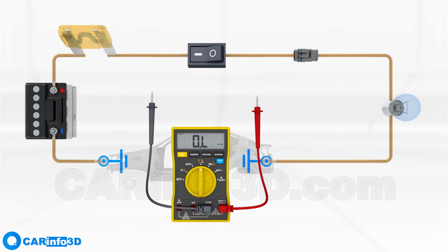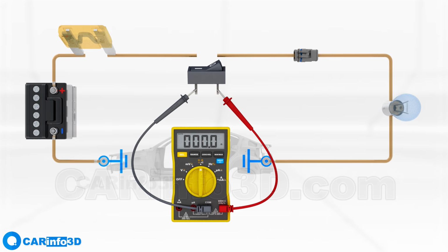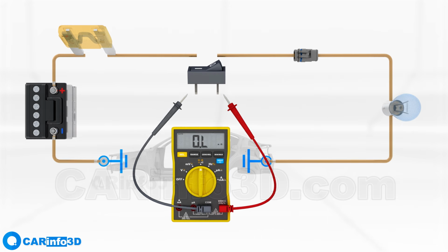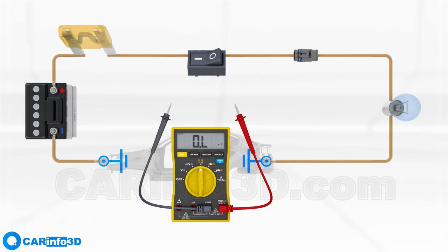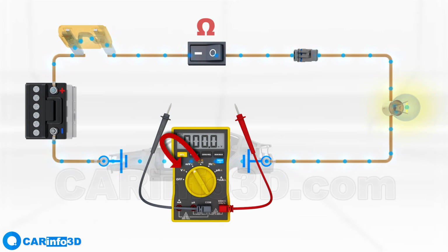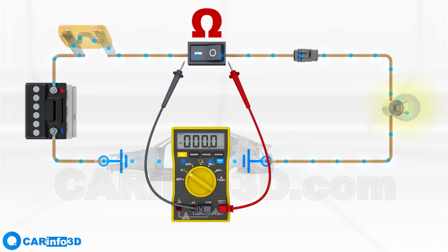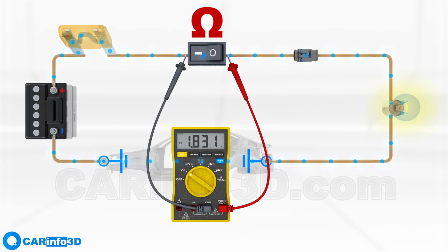Before wrapping up, it's worth noting that measuring component resistance is not a reliable way of detecting voltage drop issues. A component may test fine, but its resistance can increase significantly under load, resulting in a substantial voltage drop.